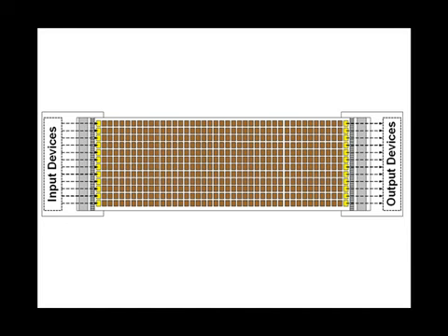In other words, the yellow relays on the left side are the electrical interface between the input devices and the control panel. So each of those yellow relays converts the on and off state of the input device to an open or closed contact for use by the brown relays. The brown relays will all be one coil voltage, 115 volts AC or 24 volts DC.